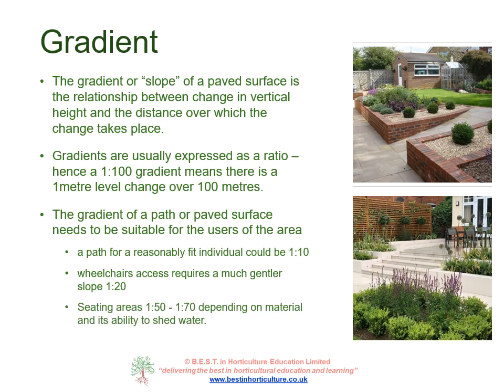Seating areas, such as patios, should have a gradient of around 1 in 50 or 1 in 70. They don't need to be completely flat, and indeed this would be impractical as the area wouldn't shed water. It also depends on the material that you'll be constructing your paved area from, as some materials are better at shedding water than others at shallow gradients. So either way, combined with levels, we need to get a good indication of what the gradients are doing on our site to make sure that we can plan our features appropriately.